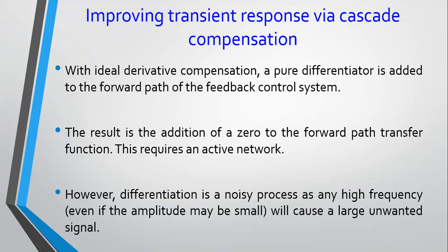So like we have commented before, if you wanted to modify the transient response of your system and the new pole you want to put it at is achievable by gain adjustment, then you would not actually need to design a controller. But in case the pole you want to put it at is not on the root locus, then it is then that you would need to design a controller.